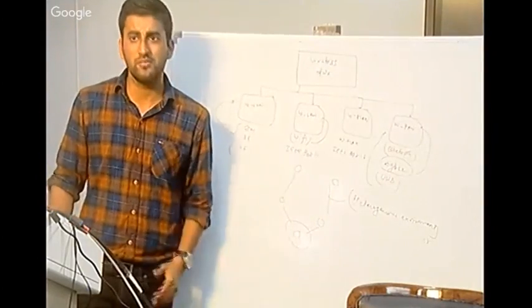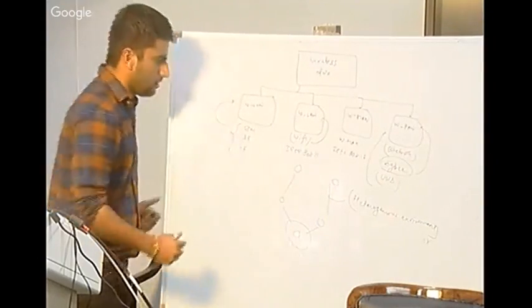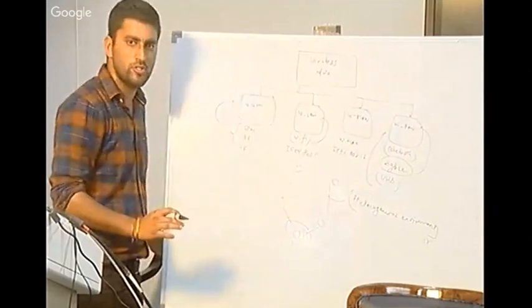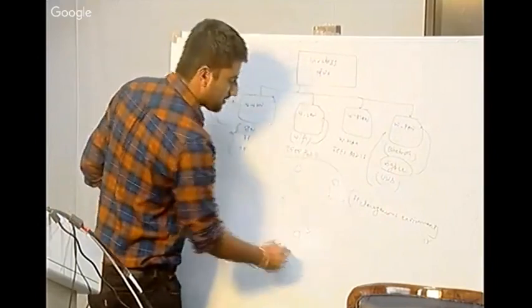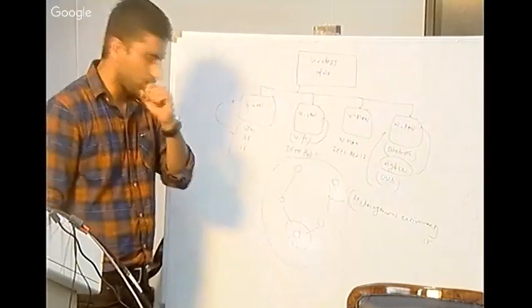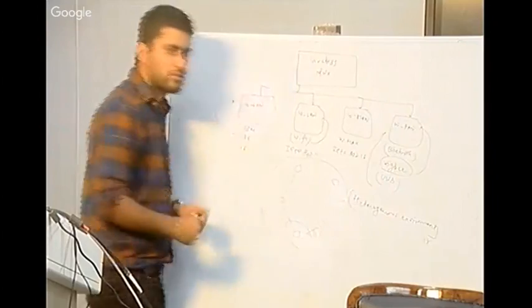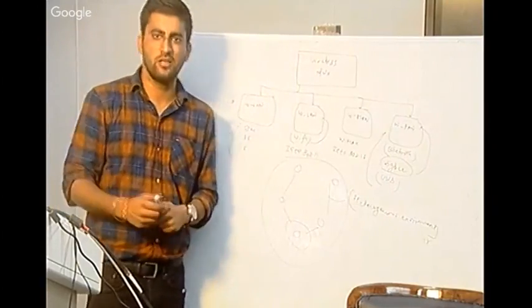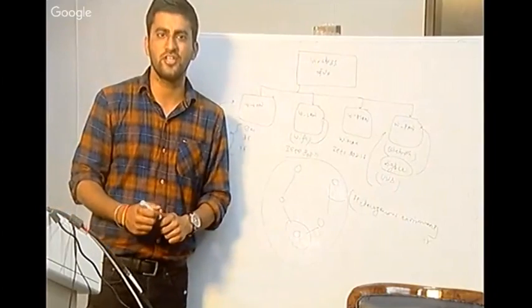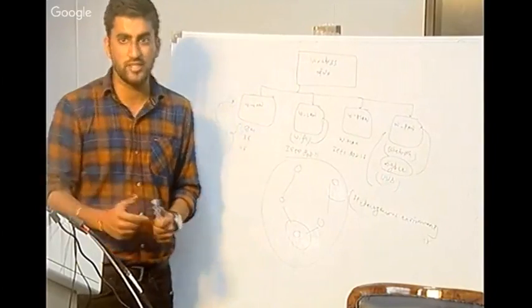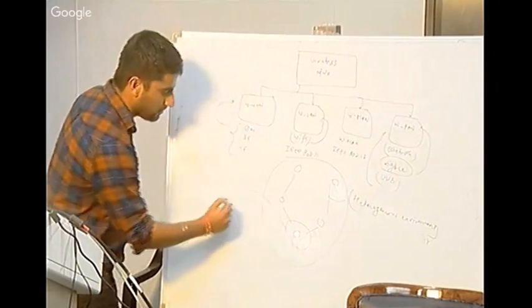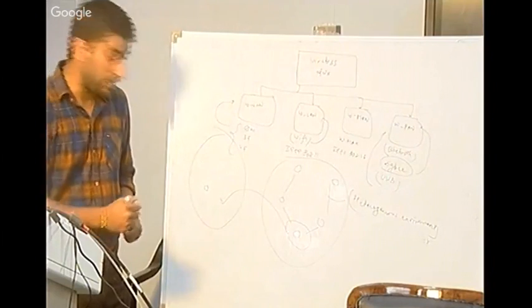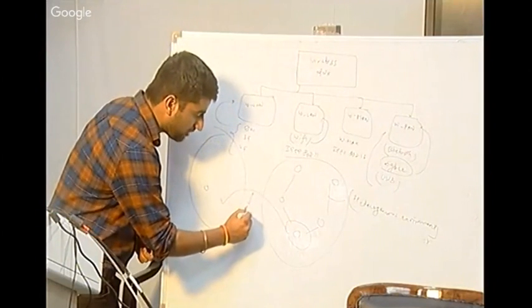I'm using the term cluster head. It means that among a huge network, for example, I have a lot of sensor nodes, and among that I'm making clusters of, let's say, 5 nodes. In that cluster I'm choosing the cluster head, which is, let's say, the king, having very high energy in order to process the data. Now in a multi-hop fashion I'm transmitting that data to the next cluster head, and in this transmission the routing protocols are involved.